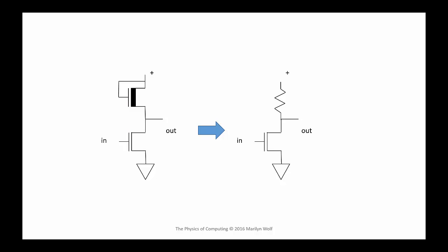Other microprocessors at the time used NMOS circuits for their logic. NMOS consumes more power than does CMOS. Here's one reason why. This shows an inverter made up of an enhancement transistor for the pull down and what's known as a depletion transistor for the pull up. The depletion mode transistor acts as a resistor. So when the enhancement mode transistor is on, there's a path from the VDD to the ground. That means that current flows even when the output is stable. That means that the NMOS logic gate is always burning power in this case.